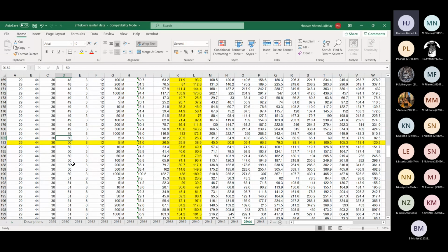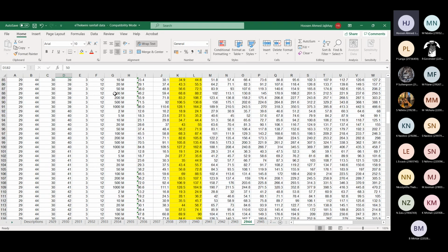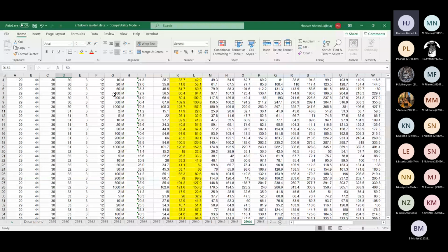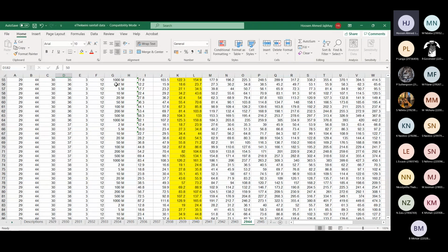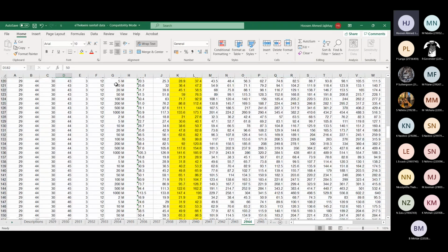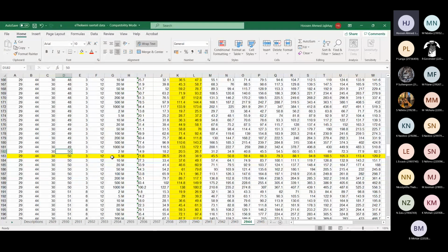Now we're looking for a, sorry, a 1 in 5 year storm. So this column G, let me go up again. That's the return period. You can see the RP I spoke about. Make a note of that. Right. So the RP is for, it's come down again now. That's why I highlighted in yellow. So we're looking at the 1 in 5 year return period. So we now have that 1 in 5 year return period, and we got the correct latitude and longitude.